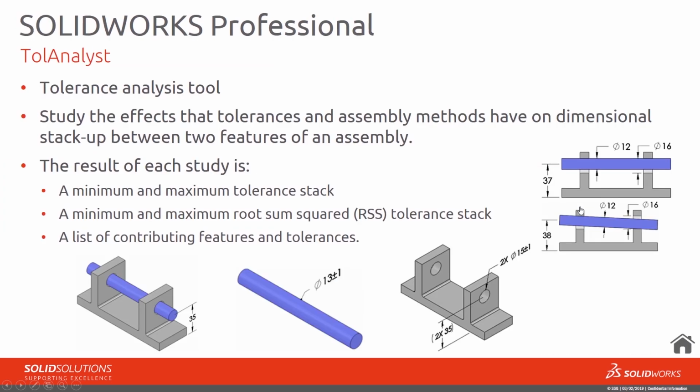We've got Tol Analyst. So this is basically a way of looking at your tolerances over models and working out what the minimum and maximum tolerance stack would be. So obviously this would be pretty difficult if you were to do this manually. So this is just an automated tool of being able to calculate things like the min and max root sum squared of tolerance stack.